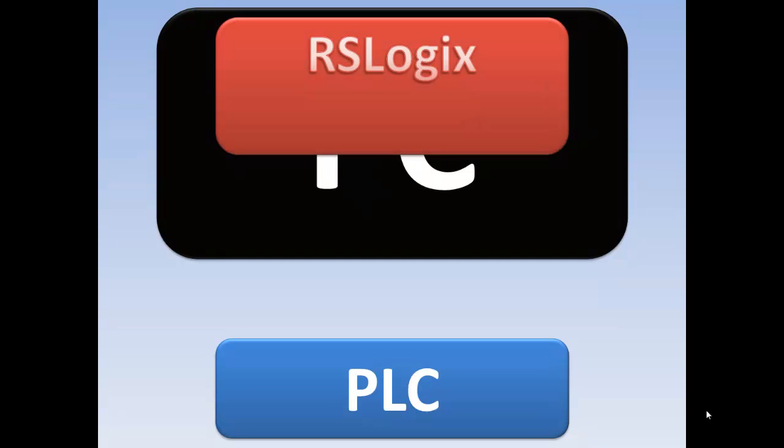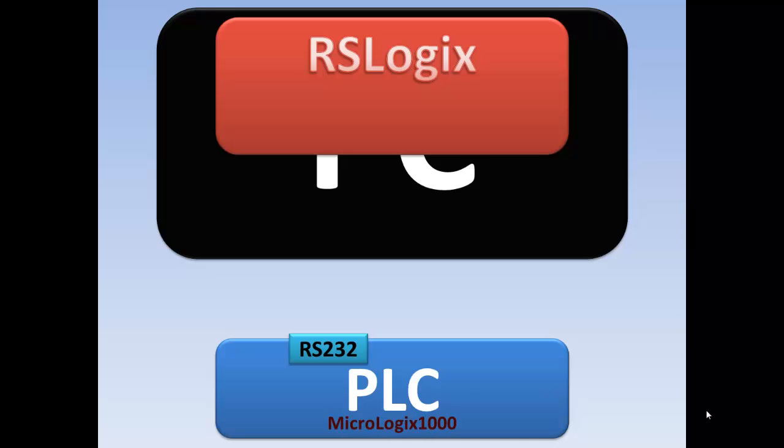In order to communicate with the PLC, in order to speak to it in its language, on our PC we need RSLogix. Some form of it, RSLogix 500 Pro, RSLogix 500 Standard, RSLogix MicroStarter, or RSLogix MicroStarter Lite. But we need RSLogix. We also need a COM port on the PLC. In this case, the PLC that we use most often in the Complete PLC Learn series is the Micrologix 1000, and it has one COM port, an RS-232 port.